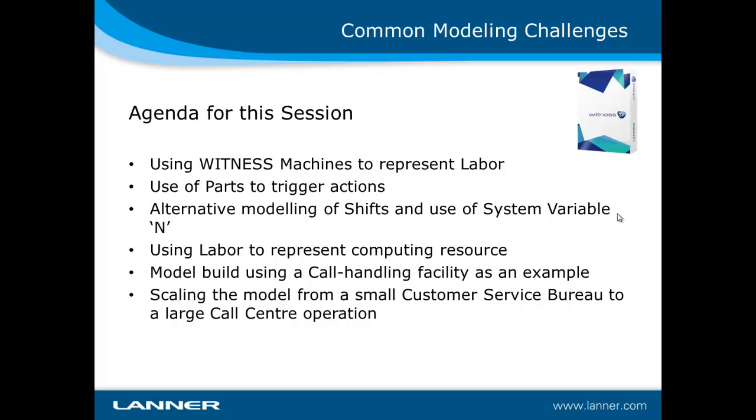Today I'm going to show you how we can use Witness machines to represent labour, so a different use of the standard machine element in Witness, use of parts to trigger actions, alternative modelling of shifts, and use of the system variable n to control the number of resources that we have in a model instead of using the shift element itself.